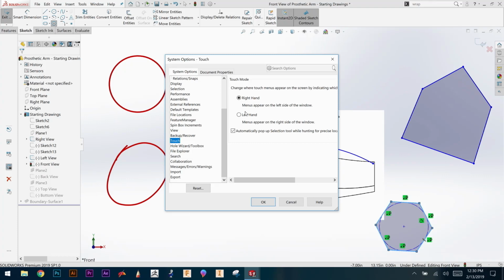I wouldn't say there's a really hard advantage of one over the other, especially since projecting uses another parametric feature to get the end geometry you're looking for. That can be really advantageous because whenever something's parametric, you're always able to go back and edit those features. But I've just gotten really comfortable drawing 3D splines, editing them right there in that spline geometry, and once I know I like it, you're good to go.